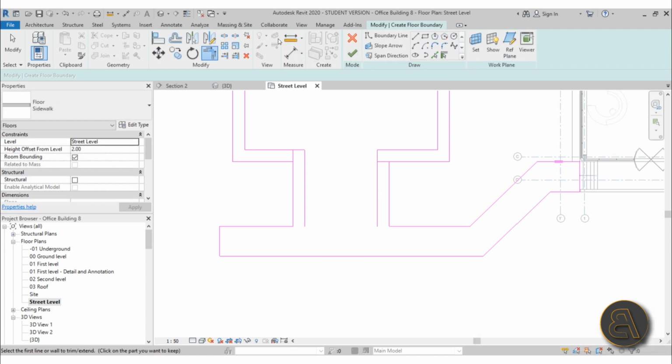And then I like to use the split line here as well. And then you go trim and extend like this. Okay, so once you have done this, then you go with the fillet arc tool, and then you fillet it as long as it makes sense. So here, it might be like 3 meters. I think it's enough, so just go to 300.